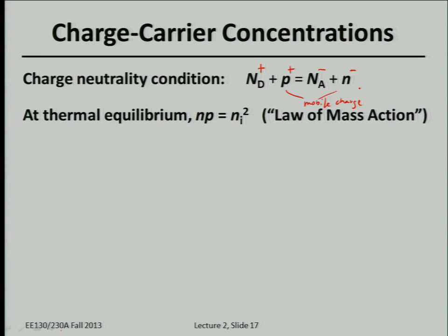So let's say if Peng were modeling an electron, and most of these seats in the classroom were empty, it's really easy for him to just sit down, right? Easy to find a seat, and then you'd basically annihilate the electron. In other words, if there are a lot of holes, then the chances of an electron recombining with a hole go up, and so the concentration of electrons goes down.